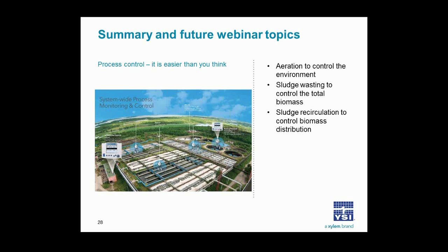But also, of course, with age, the sensor optics are going to age a little bit, and that's going to be a much slower process, but you'll know when you're drifting apart by keeping a good record of verification measurements with, for example, a calibrated handheld or grab samples measured with good laboratory practice in the lab. And that's how you'll know when it's time to calibrate your TSS sensor.